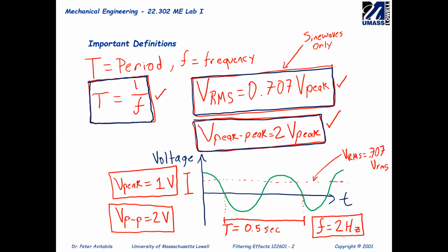Because we were supposed to be recording the voltage peak, you could also get that from dividing the peak to peak voltage by 2, correct? Yes. So what if those two numbers are different? For example, on channel 1 we have the voltage peak to peak as 14.6, so the voltage peak should be 7.3. Yep. But then the voltage RMS was 5.4 volts RMS, and that divided by the magic number is 7.637. Correct.